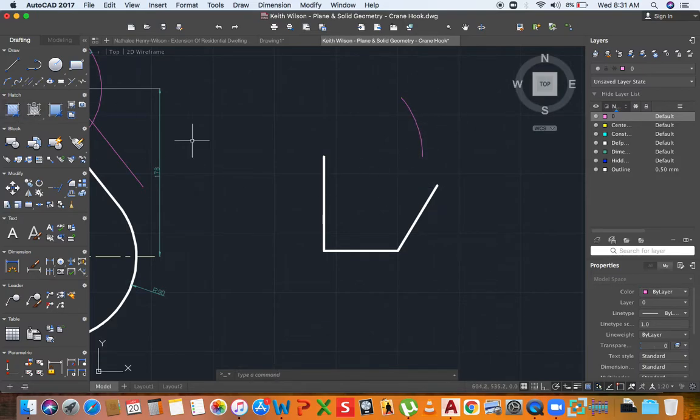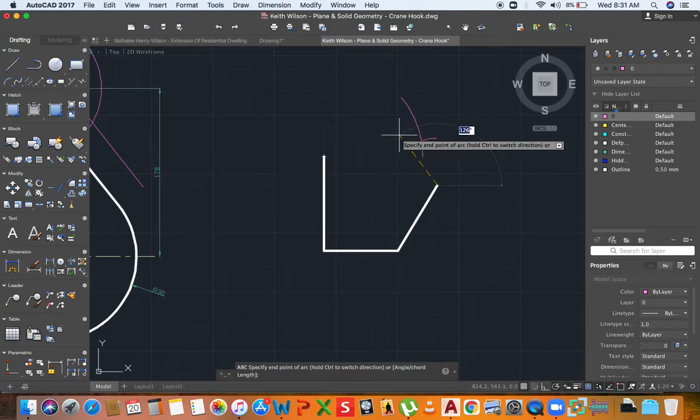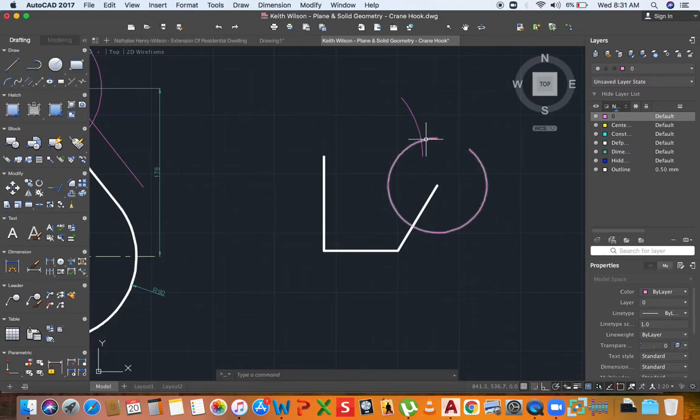Then for the next side, from here to anywhere on this arc is 100. So what I'm going to do now is select the arc command again, then press C, enter, click here where point C is, and I'm going to type 50 because that's the length of CD. And I'm going to type 50, press enter. Hold on, let me do that again.